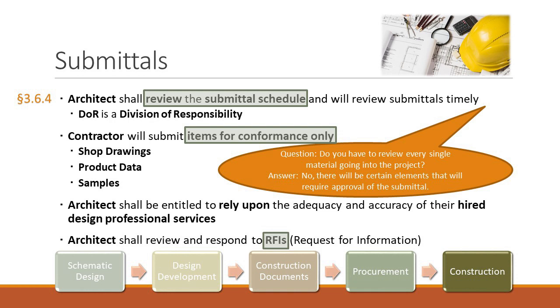Okay, the last part here is kind of a repeat. It says, your review shall not constitute any approval of safety, means, methods, techniques. So if they say this is how they're going to do the bolt diagram, it looks like it's supposed to be, but I'm not saying it's safe, and I'm not saying that the bolt diagram's right because I'm not telling you how to crank those bolts down. I'm just saying it looks like it should be for the design concept of the drawings. It's not an approval of the assembly. So you kind of have some more get-out-of-jail-free cards here.